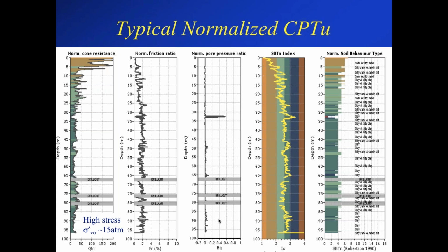And then it says, what method was used to determine P and S wave velocity? So it was seismic CPT, and this is a downhole method. You push the cone in, and basically every meter you add another rod, and during those pauses you can generate either a P wave, or compression wave, or a shear wave at the surface.